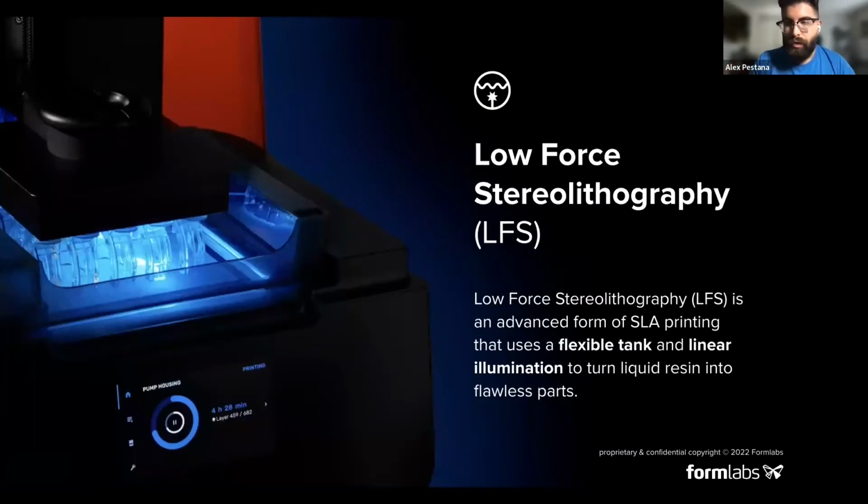So just double clicking a little bit more on what we've done to fine tune this process. Form 1 and Form 2 were that traditional SLA process with a lot of different mirrors and galvos, which worked great. And it's how traditional SLA is done. But we're always talking about how to make things easier to use, faster and such. So we developed a process called low force stereolithography, which uses a flexible tank and an integrated light processing unit called an LPU, which allows for a lot less calibration and doesn't need to be as sterile of an environment.